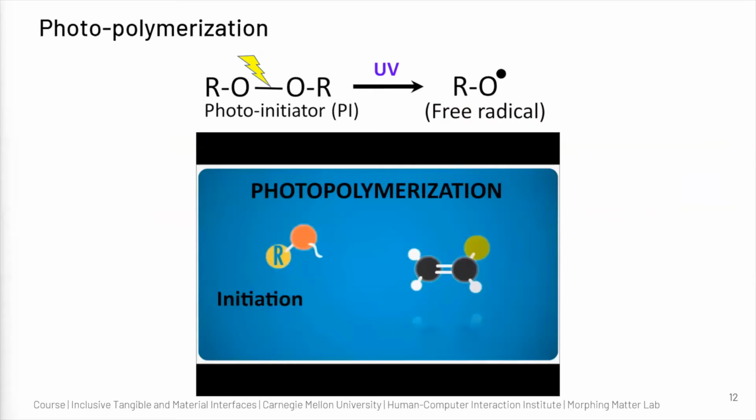Now, I have used photopolymerization or photopolymers in a couple of printing techniques, so we should also understand how the process works. Whenever you hear the word polymerization or polymer, three things should come to mind, like the reaction steps. The first step is called initiation. The second step is called propagation. And the third step is called termination. So now let's go into details of this.